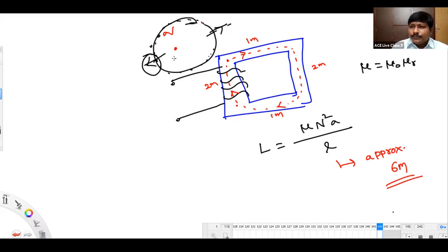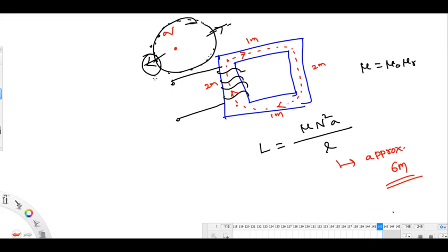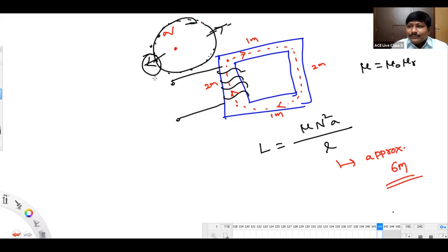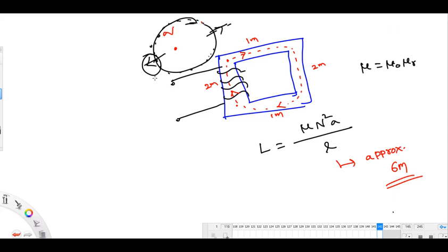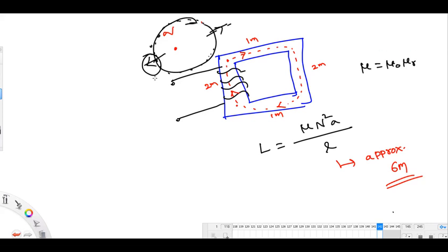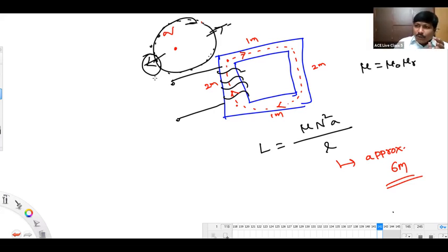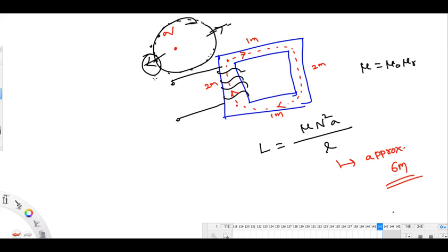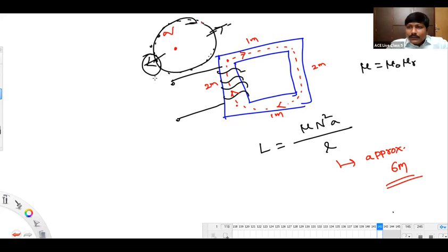Then what happens actually? Obviously the net flux is leaving out only. But we studied it with the minus Q charge. Actually, listen, ground is assumed as a zero potential plane after this explanation, not before this. We are keeping a charge inside the ground, and with the effect of the charge, the Earth as a whole is going to act as a charge only. So you are keeping a charge inside the ground, and with the effect of that, it will be acting as a charge only.